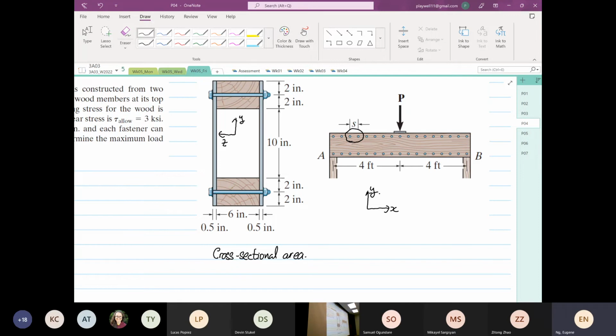Right. Likewise for this, okay? We know the load that we're going to carry. Okay, the trick is, what is the spacing of the screws? How much spacing do you have to go? If you're not sure, what will you do? Every fist palm distance, I put one screw. Right? How many nails are you going to use? Is it going to be a big deck? No. Okay. There's a reason for how many screws to put in, based on how much force is required to extract your nail or your screws. Okay. So there are reasons for design.